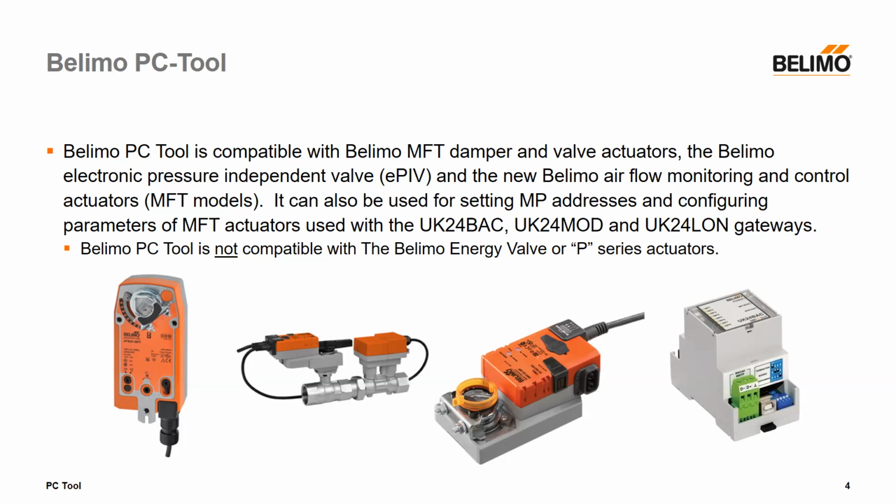And we also recently introduced the Belimo airflow monitoring and control actuator. It's similar to a VAV style actuator, and PC Tool is also compatible with the MFT versions of that. You would need a release code, just a little plugin that goes into PC Tool to be able to set the maximum and minimum airflow values in CFM. That's something we can dig into a little deeper at a later time.